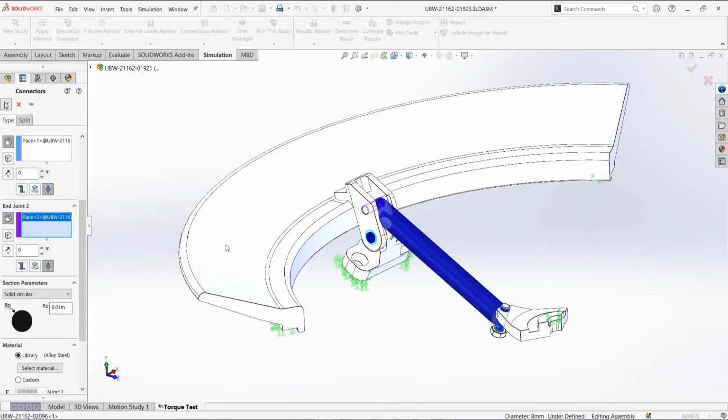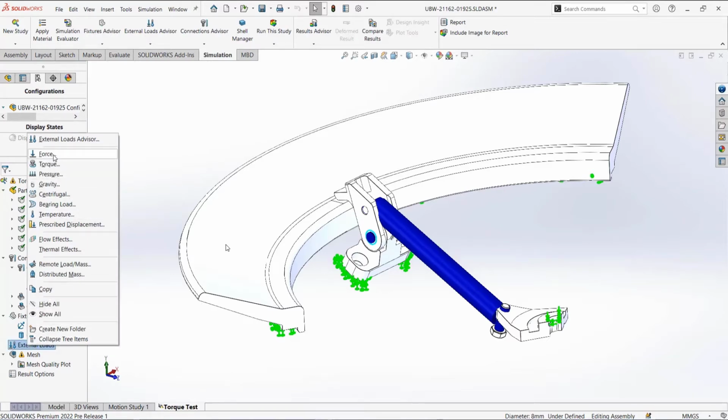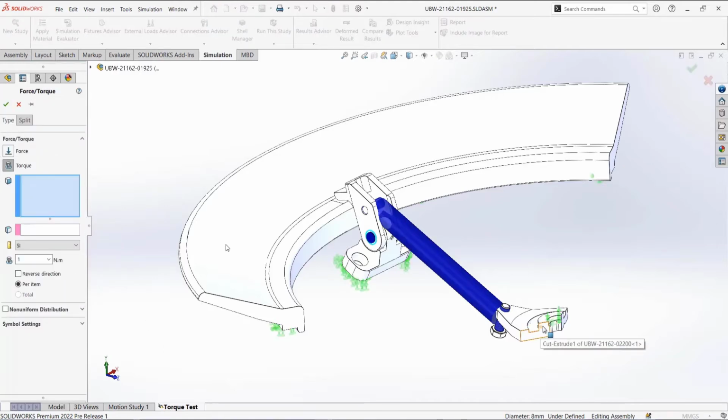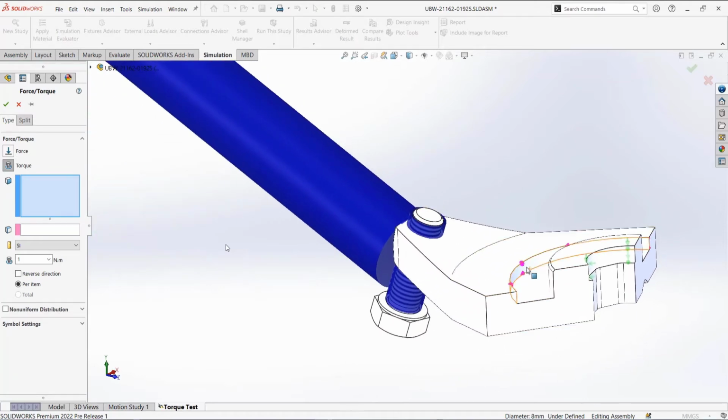Here I'll consider 1 centimeter as the reference diameter. To seal this, a human should apply 16.5 Newton-meter torque on the handle. So I'll select the reference faces and define accordingly. Torque on this one, so I'm considering one-third of this, so I can take 16.5 divided by 3. The value is 5.5. I'll consider that value here.